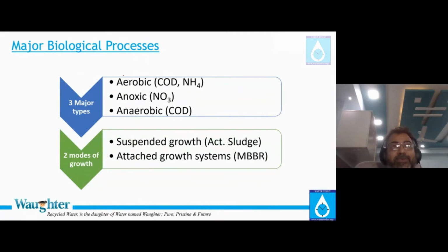And yesterday's question, now somebody is asking me, I don't remember all the names, because I know no names individually, but who asked which question, I don't remember. Did I talk about BOD till now? So please believe me, for becoming a wastewater treatment expert, you don't even have to talk BOD. All calculations, all formulas, all thinking, all estimations are done on COD, because C is the pollution in and the measurement form is OD, oxygen demand of that carbonaceous material.